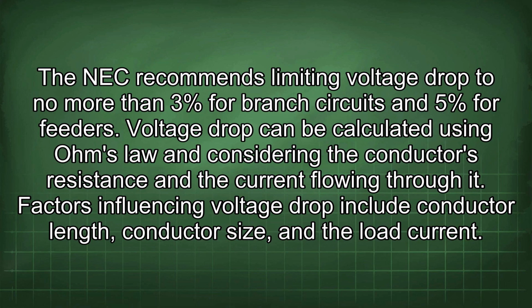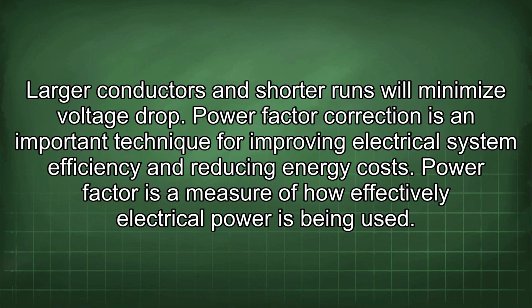Voltage drop can be calculated using Ohm's law and considering the conductor's resistance and the current flowing through it. Factors influencing voltage drop include conductor length, conductor size, and the load current. Larger conductors and shorter runs will minimize voltage drop.